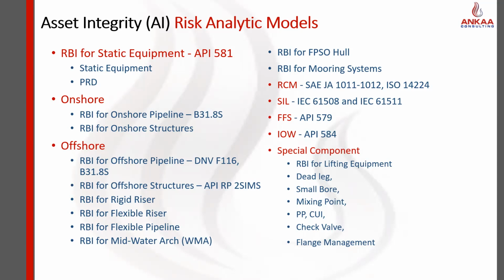analytics tools which are very specific to the damage mechanisms. So that they're not generally done outside, and then the data is used in the FFS modules to do your assessment. So the consequence modeling and so on is done outside the FFS module for Level 3, but you can do the assessments. And then you've got the IOW, as I mentioned earlier on, based on API 584.